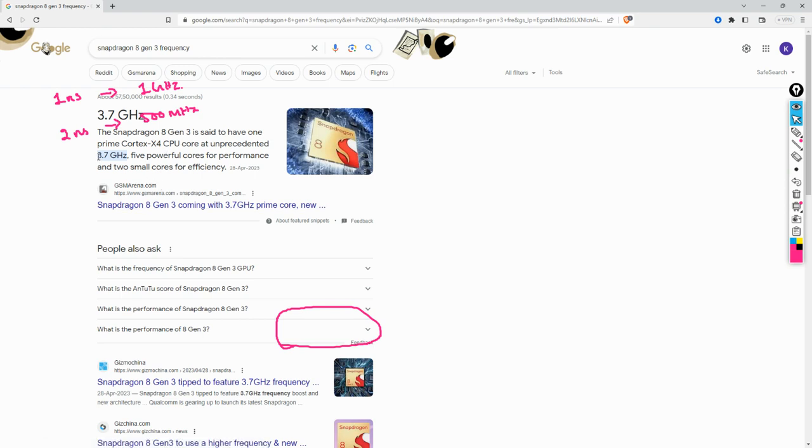You see here, there is a 3.7 gigahertz. Okay, now what would be your period here? 3.7 gigahertz. What would be your clock period here? Approximately 0.27 nanoseconds. Okay. So you're saying it is basically 270 PS.